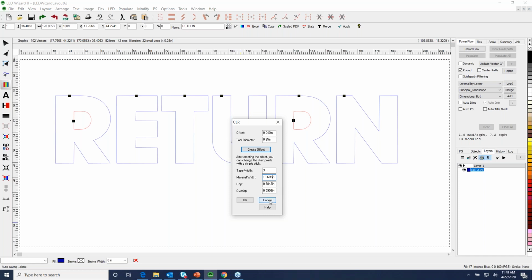Material width is actually the plottable size of your plotter. The assumption is that you're plotting these patterns. Some of these patterns can get very long, so you have to make sure you have good tracking on your plotter. Some customers will also print these, some on vinyl, which is expensive, but that's an option too. So material width, because these are nested.